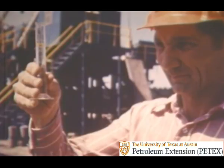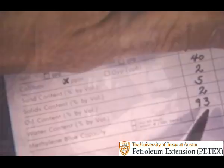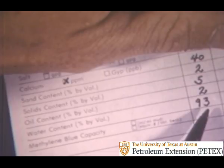The liquids are condensed into a graduated cylinder, and the percent by volume of oil and water is calculated. Then the amount of calcium in parts per million, 40 in this case, the sand content, 2%, the solids content, 5%, the oil content, 2%, and the water content, 93%, are all entered on the report form.